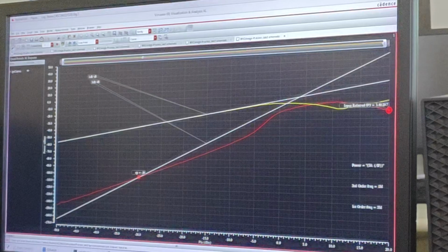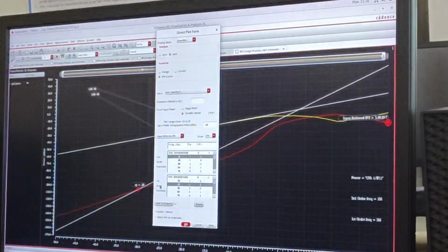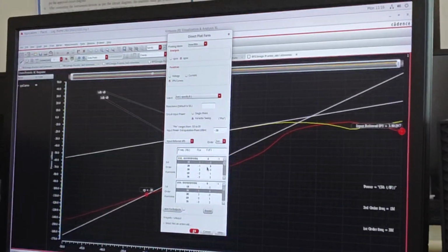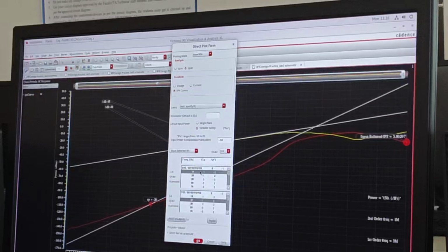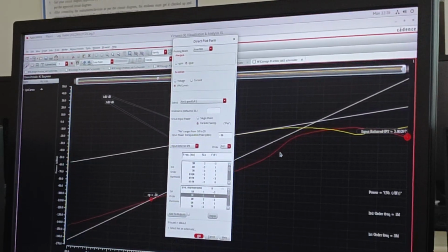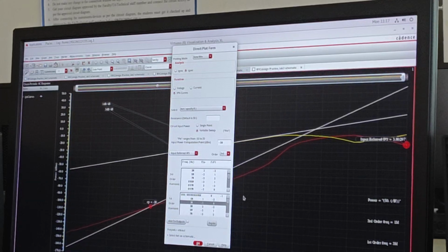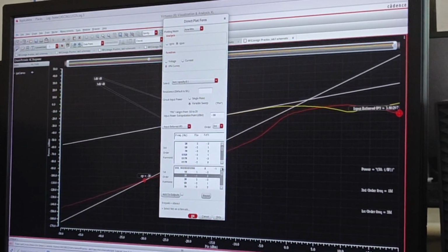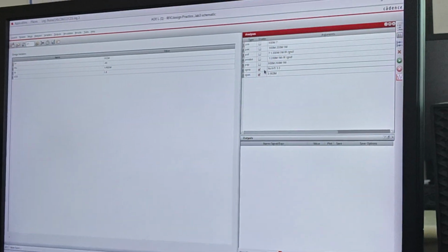Okay, but the simulation procedure is the same. Just select these harmonics: what is the first order harmonic and the third order harmonic, and where exactly it is coming. While selecting, please select this properly. Mostly it will extrapolate properly. If it's not, just go to lower input power and check whether it is coming out linear or not.